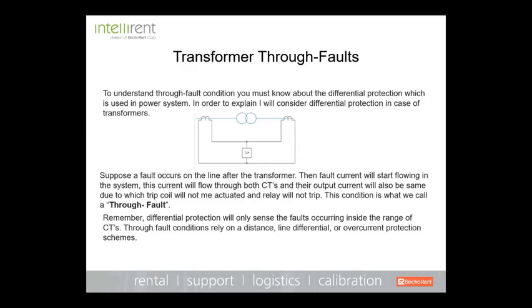Now you will protect it against catastrophic failure or a serious failure that would result in a fire or an explosion. But for the most part, if your differential relay trips from a true fault within the transformer itself, you've already got that problem. Now, there are protective elements, such as volts per hertz or thermal protection on that transformer that will keep it from becoming damaged due to certain system conditions, but not through faults.